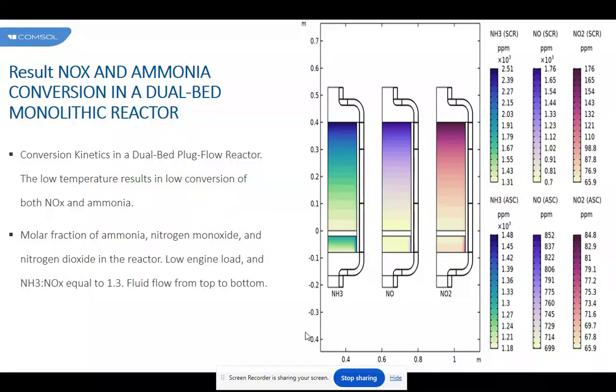The washcoat typically occupies about 12% by volume of the monolith. The cell density and wall thickness dictate the channel size, which combined with the washcoat loading govern the open frontal area, which is equal to the monolith porosity.